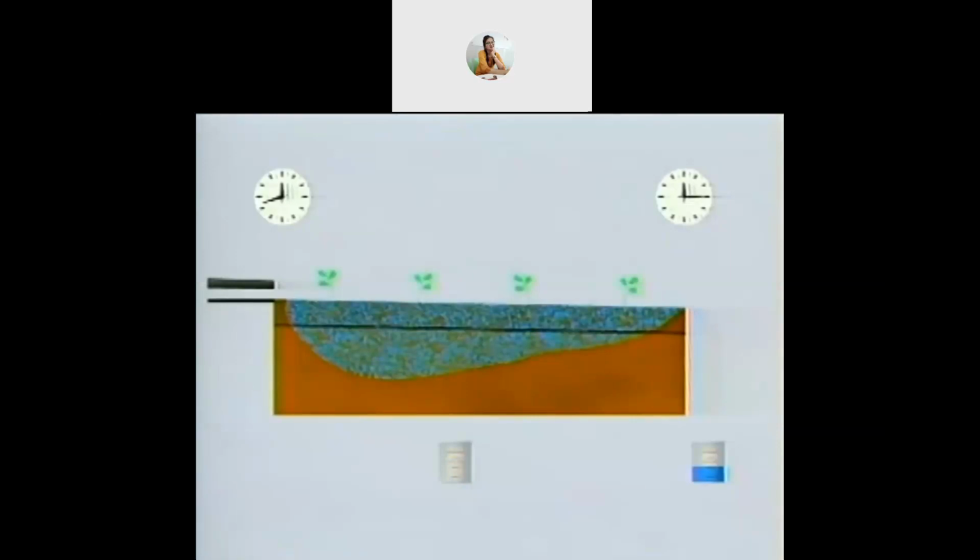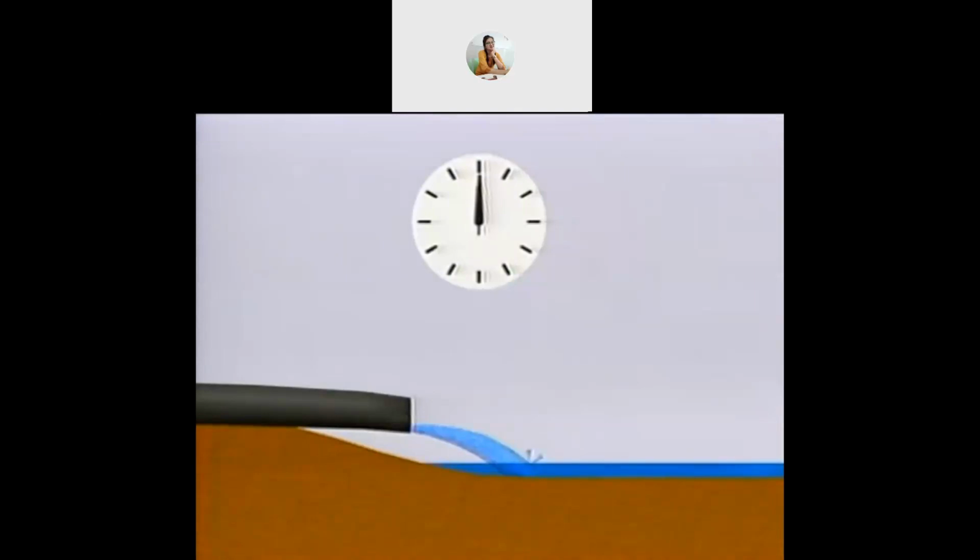This irrigation has high uniformity, but too much water was applied, resulting in water lost to deep percolation. This field is just right. Unfortunately, it's also impossible. We have learned about uniformity, deep percolation, and runoff, and how they affect how much water is wasted. But how do you control them? You can control two things: set time and flow rate. Let's look at how set time and flow rate affect your irrigation.